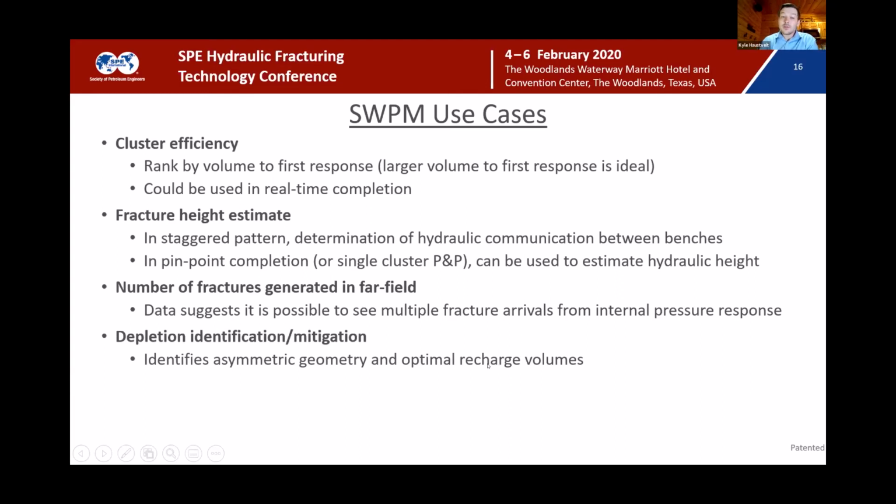We've used it quite a few times to understand the impacts of depletion. So if you're drilling and completing a well next to depletion, is that depletion pulling your completion back towards the lower pressure sink? If so, how do you overcome that? Is it a recharge? Is it a refrac? Can you do anything to your new completion to try to limit that?